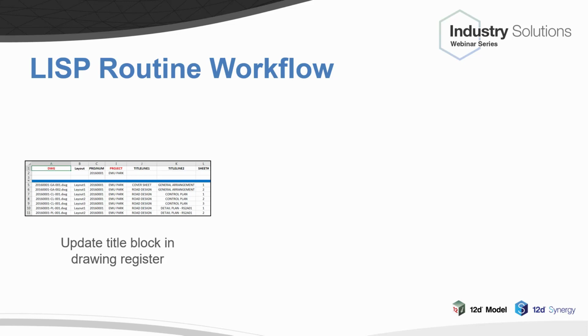Now this is so much easier than doing it manually because now you have copy and paste, drag and drop. All he has to do is edit that one cell and then you can drag it onto all others and that's it, you mass update it. It's also a lot more accurate because now you're only changing one cell rather than all the title blocks. So there's a lot less likelihood for error. And if an error does occur, it's a lot easier to see and then to change because all your title blocks are visualized on your screen in one single spreadsheet.